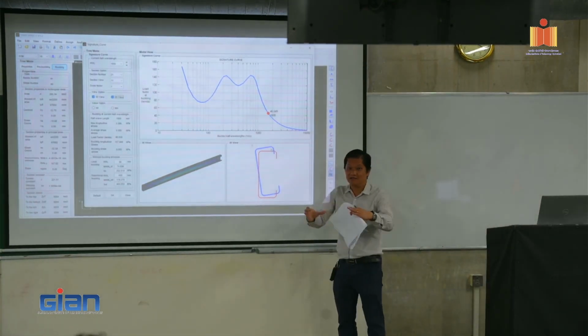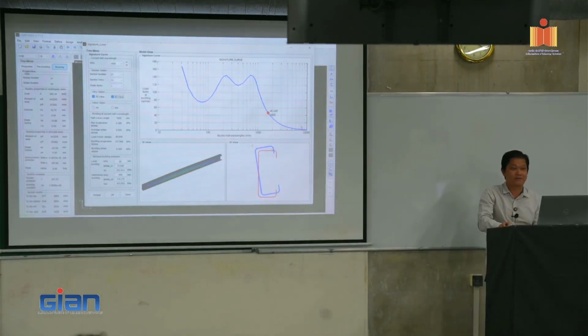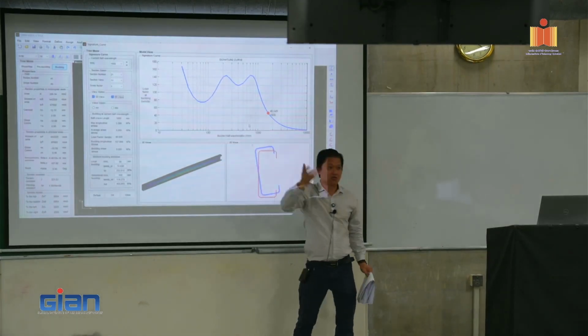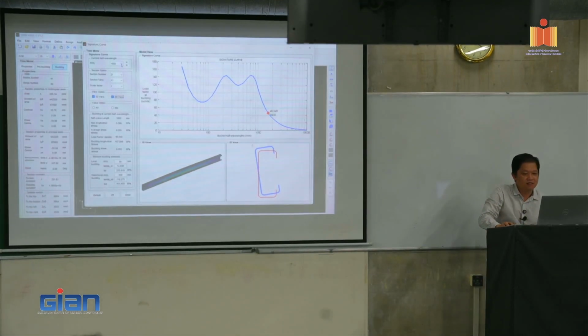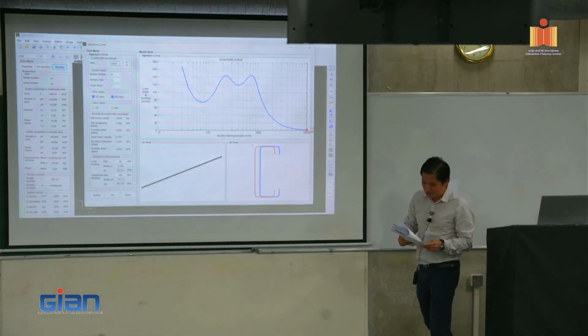That's why it gives a lot stronger or stiffer distortional buckling. So it gives you a push that moves the half-wavelength, that local-distortional minimum point, up. All right, so that's what I want. It's purely flexural. Yeah, that's what I want to show you.